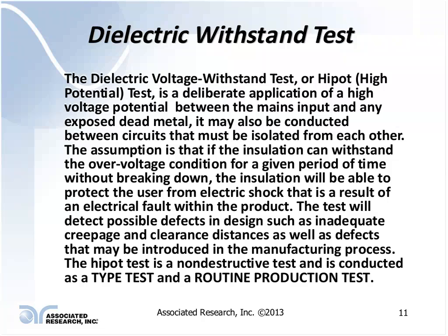The test is designed to find possible defects in the design, such as inadequate creepage and clearance distances, as well as defects in the production process, such as pinched wires, damaged insulation, potential spacing problems and so on.